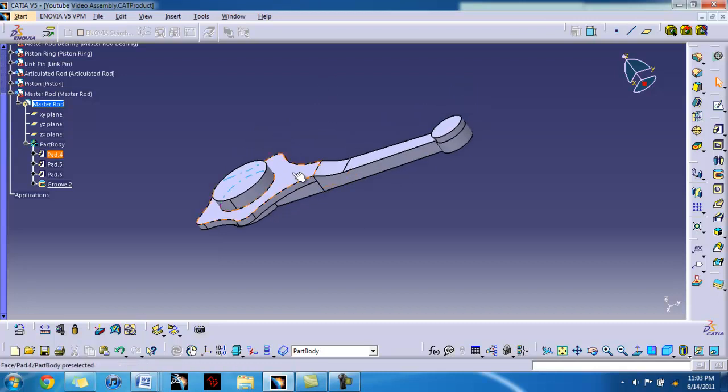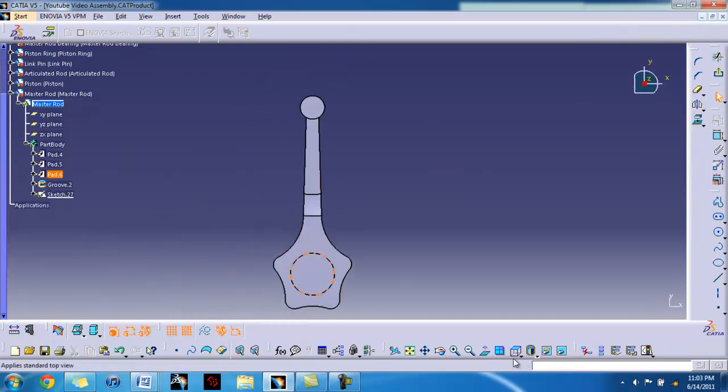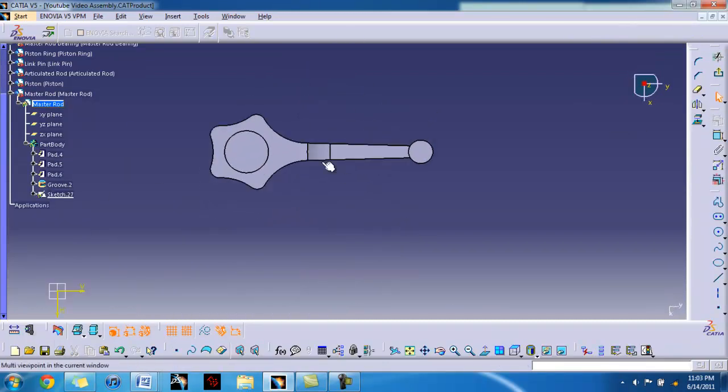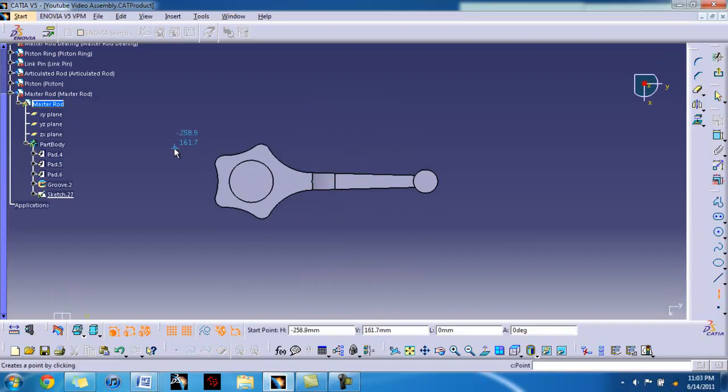Now we're going to do the elongated hole. It starts from the top, so we're going to go into the sketcher in the top face, from top view again, creating another centerline axis. We're going to constrain it the same way we have before.